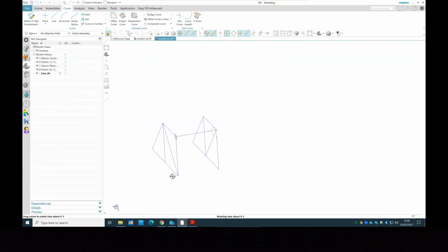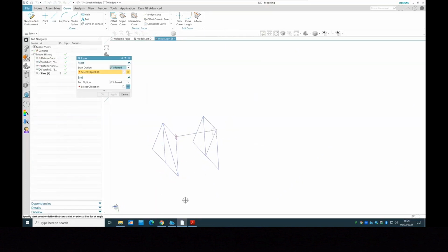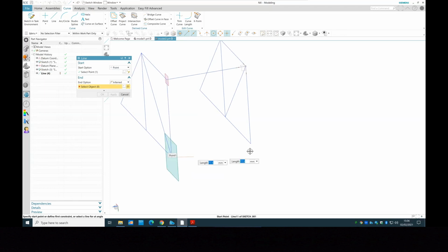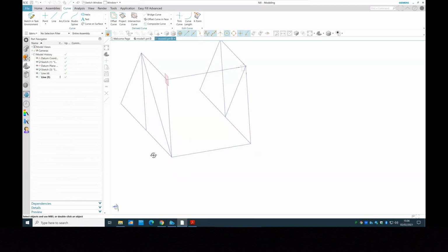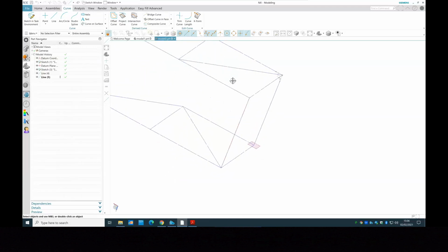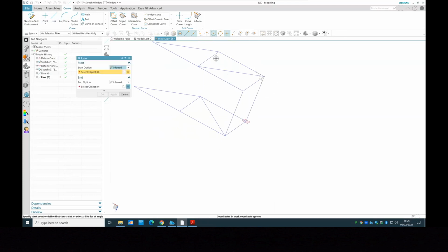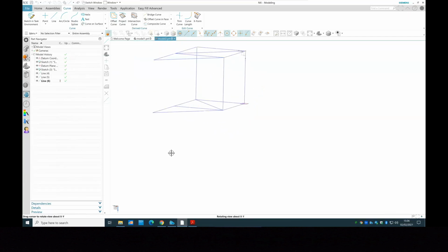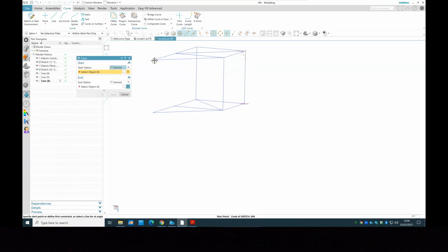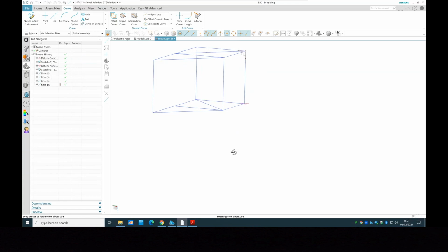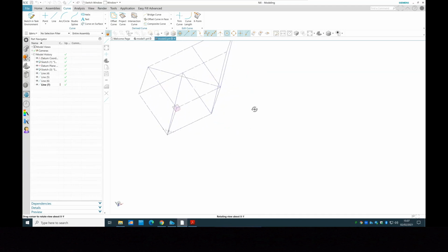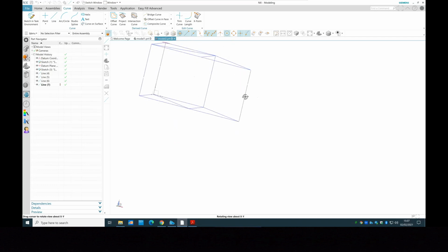And you just make a line on the top, make the line on the bottom. So you can see I close the back. What I'm gonna do, I'm gonna close the top as well with the same sort of technique. I will click there, I will click there as well. Close the top. I want to close the front of it as well, and I will draw a line from here to there. But make sure whenever you do that, you rotate it to make sure actually you pick the right plane for you. And what I'm gonna do, I'm gonna close the back as well.